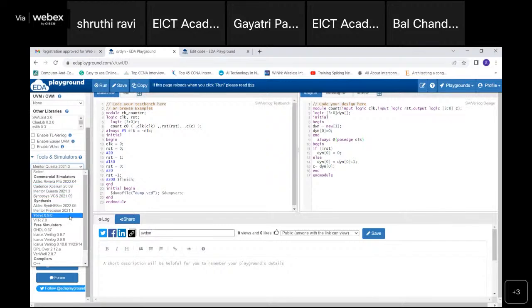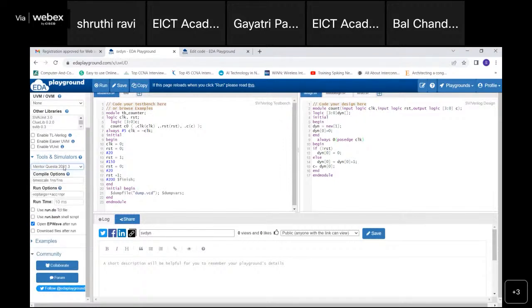This one helps me simulate System Verilog very effectively. Not all support System Verilog as effectively. Icarus is mainly useful for Verilog operations. Then we can select the time scale for simulation as per the requirement.